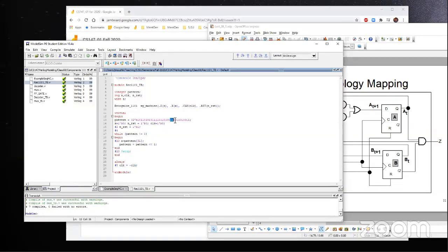And maybe at the 1101, this one will be high. So 3 blips maybe, I think so. Yeah. And to start with, I have X, the input bit pattern, at 0 and the reset signal at 0 and the clock also set to logic 0. Then at 2 nanoseconds, I am setting that reset signal to 1.